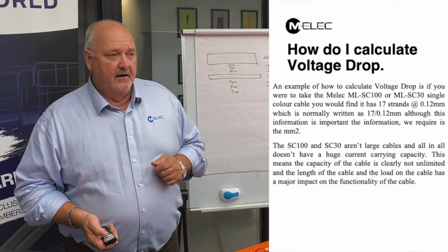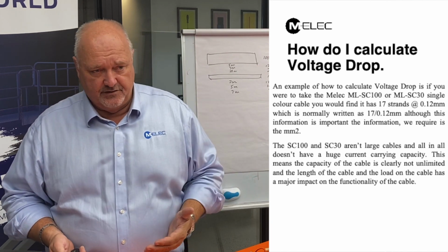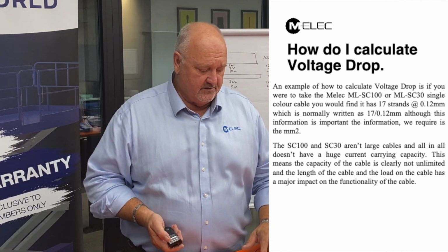The controller does not limit that. It's the cable that limits that. And that's where we talk about voltage drop. And this is where we go into voltage drop again. We go through the process of how to calculate voltage drop, why it's important and things like that.